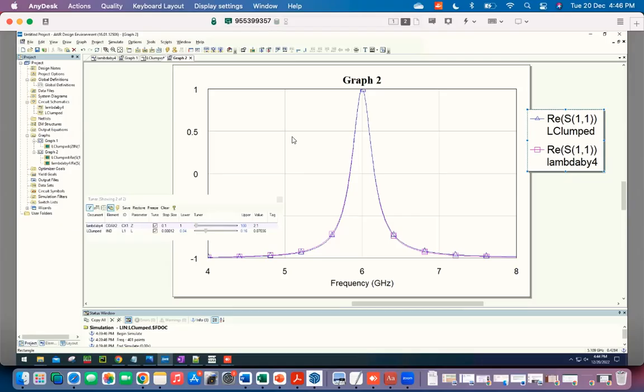On the other end also, we have this problem that if you want very low capacitance per unit length and very high inductance, then the lines become very narrow. And then in some sense, they don't see the ground plane anymore, and then they can just be like a piece of antenna which is radiating energy into free space. That is also a problem, because you don't want the energy from the transmission line to be radiating into free space, because that will be a form of loss in the transmission line. So when it comes to designing transmission line resonators, you are restricted to roughly 20 to 100 ohms. Even the extreme ends are not so great. Essentially 50 ohm transmission lines or somewhere nearby is what we get.